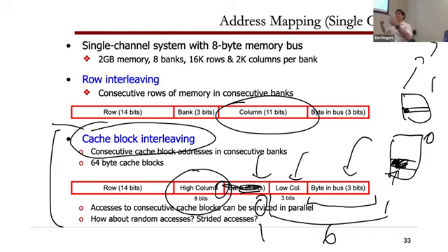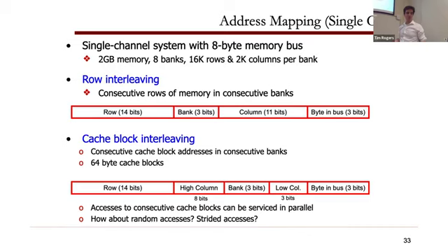And then I put the 8th cache block in that same row. So essentially, if you pulled out one row of your DRAM, you're getting cache block 0, and then cache block 8, and then cache block 16, etc., because you're spraying the blocks across the banks. And all you have to do is this weird kind of address mapping, and you can achieve that level of parallelism. This is a static thing that's done when the memory system is trying to figure out how to do this. Does this make sense?